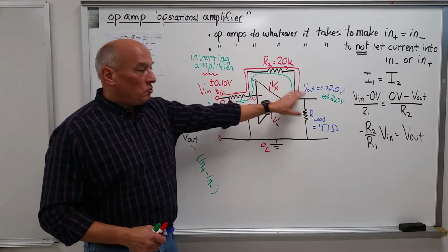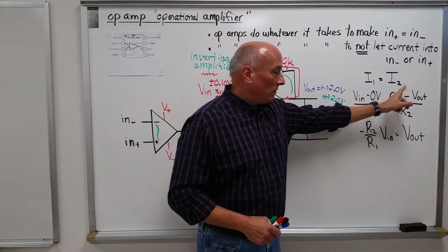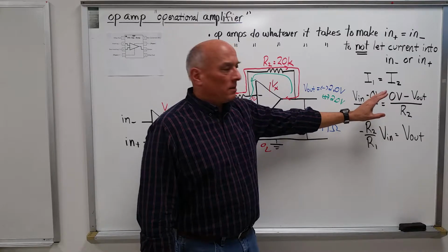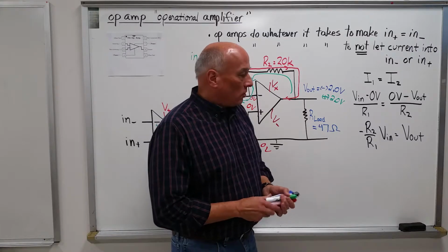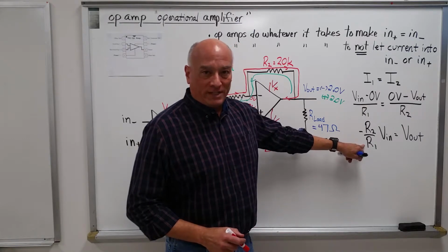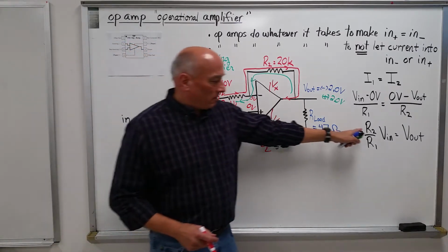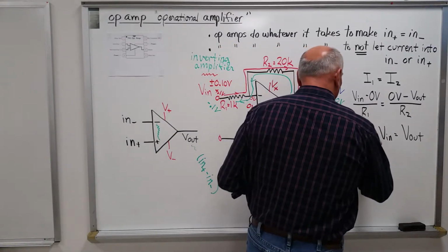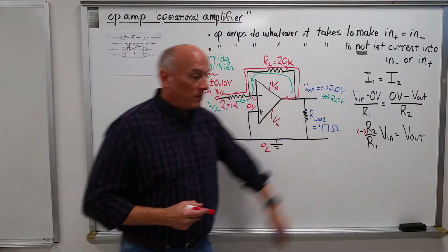The voltage across here, you cannot say V out. You've got to say 0 volts minus V out. Delta V, 0 volts minus V out. That minus is important because now that you've got this written out, those zeros and that minus sign come into play. But look what happens. You have a situation where your output voltage is amplified by the ratio of those two resistors. Conceptually it was okay, but mathematically it works out. It's amplified in magnitude by those two resistors, and this negative sign inverts it. So it's an inverting amplifier sitting over here.